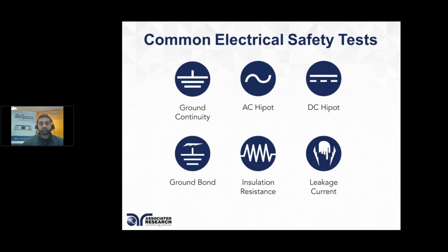to the insulation. Some of the other tests, also known as touch current or leakage current testing, apply mostly to the medical industry or medical device testing, and this is a standard that will call out any kind of leakage current test while the device is powered up. The biggest difference between all the other tests and the leakage current test is that the device is actually powering up in a normal condition, and we're checking to see if any current could make it to the surface of the product while the device is powered on. And we'll discuss this in detail throughout this webinar.